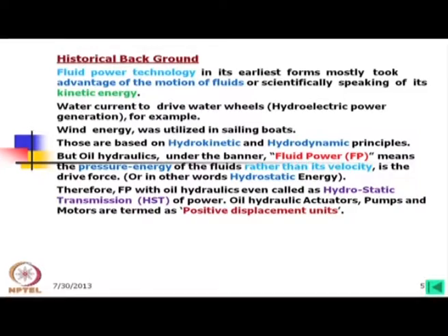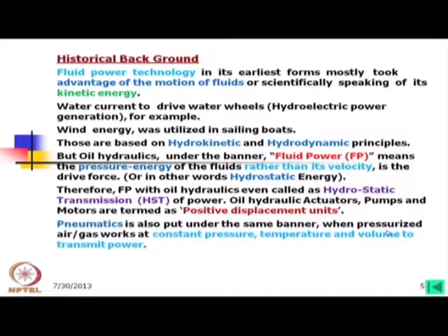The question is there, do we use any hydrokinetic principle of fluids in case of fluid power? Answer is yes. When we are analyzing the valve flow, particularly flow in and flow out, we have to use also hydrokinetic part. But as far as the power transmission is concerned, only we are using hydrostatic power. Pneumatics is also put under the same banner when pressurized air gas works at constant pressure, temperature and volume to transmit power.